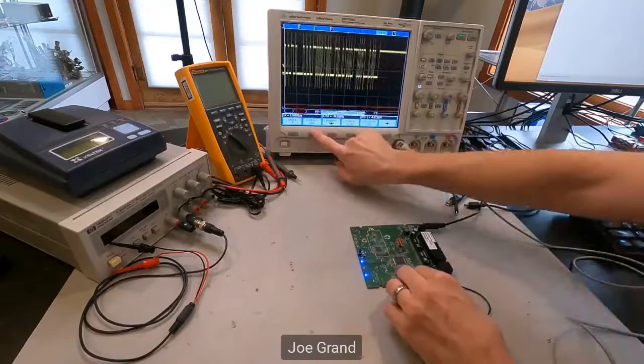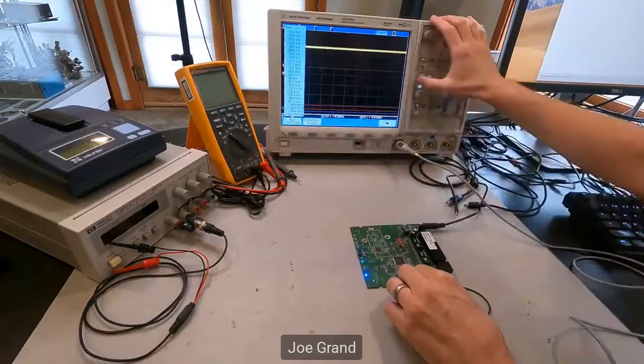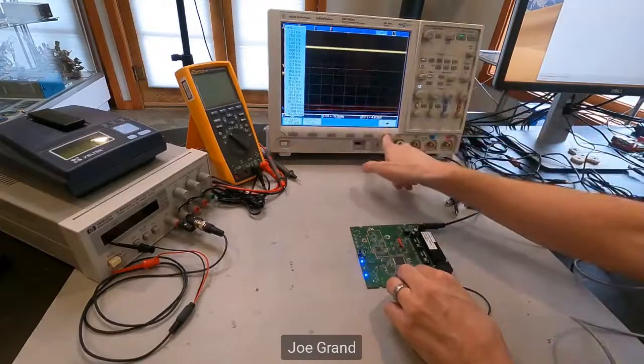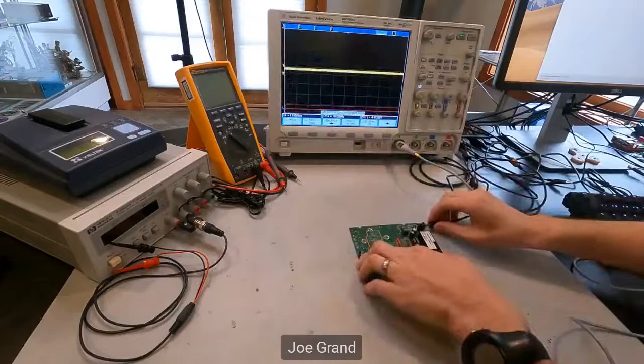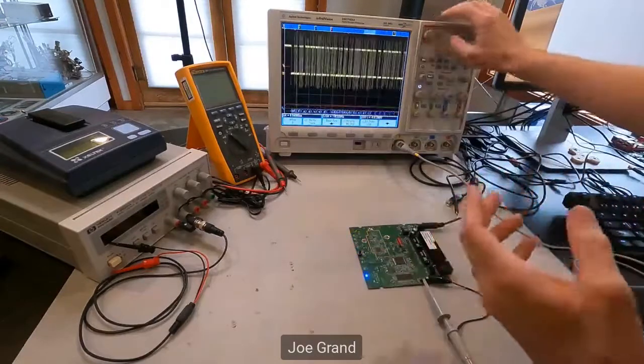Did I change my bus configuration? Let's see. My baud rate is wrong on my oscilloscope. So once we measure that bit width, we can set it to 115.2 kilobits a second. Sorry, we'll run that again. And we should be able to see some actually human readable, interesting text.